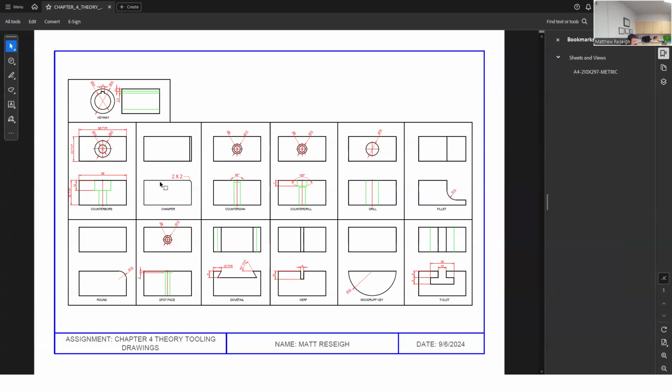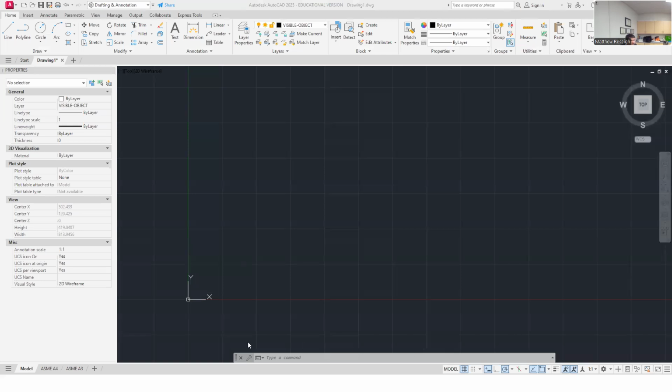So what I'm going to do is an array of that little block pattern. I might draw a top and one single one, copy it, and then array those two to make this grid. That's going to be 1, 2, 3, 4, 5, 6 by 2. Essentially, my array pattern would be 6 columns and 2 rows. So I'm heading in that direction when I jump over here. I'll keep this up on my other screen so that I can see.